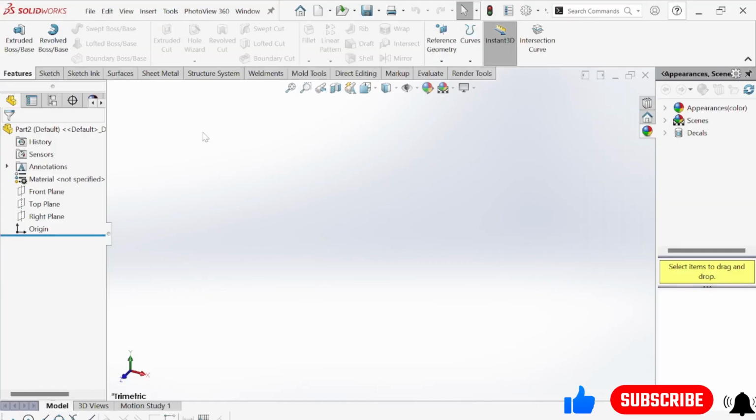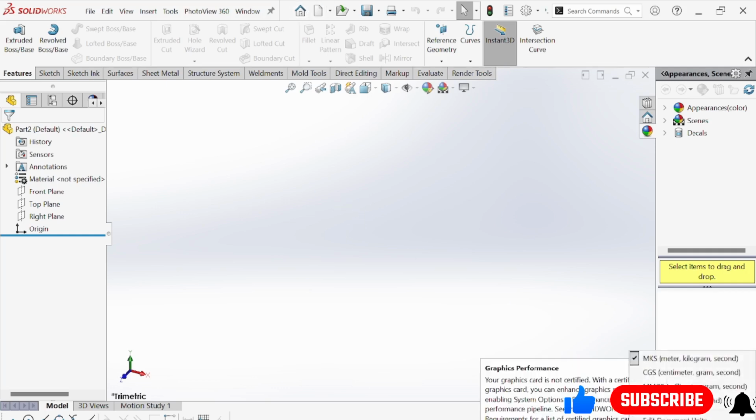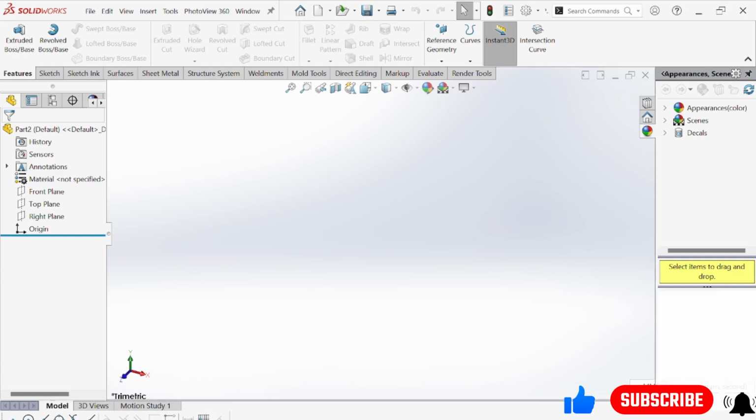So here we have SolidWorks 2022 and I have opened a new file. In this file, we are going to make the design. First of all, we need to define the units in which we are going to work. We have to check MMGS because it's a small part, just for the fitting of pipes. So let's start.